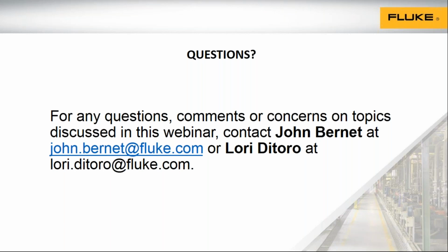Now, I'm not saying this is good for all machines either, because keep in mind best practices means we need to look at all machinery. There are some machines, for example, some of our redundant or basically our throwaway motors and pumps and fans that aren't cost effective to spend time trending or monitoring over time. In that case, planned maintenance using either a calendar or runtime is perfectly acceptable and probably preferred, because on a lot of your small, throwaway, non-critical machines, we don't want to spend time monitoring. Runtime is probably the perfect application.